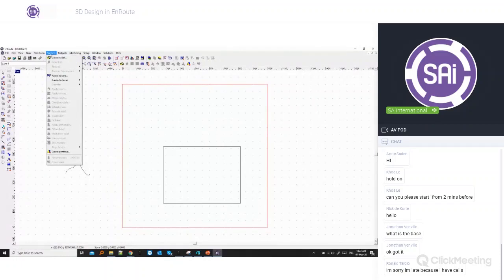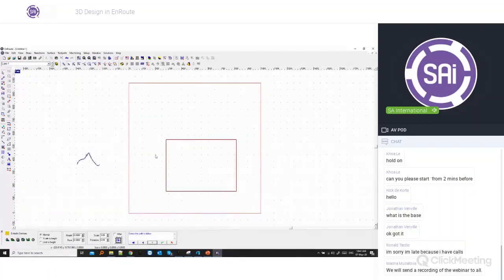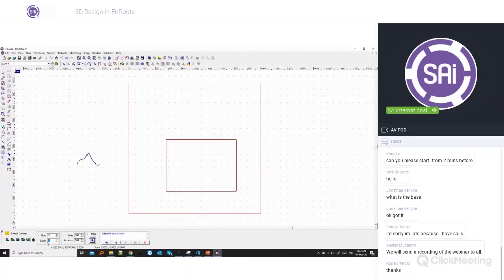Going into the surface menu, create surface and choose our extrude tool. Here the wizard will show you to select the contours that you'd like to extrude and the path that should be followed. Because we have no existing relief, I'm just going to choose to produce a mesh. And then the stacks will be the sections along the path to follow. So let me just create 300.